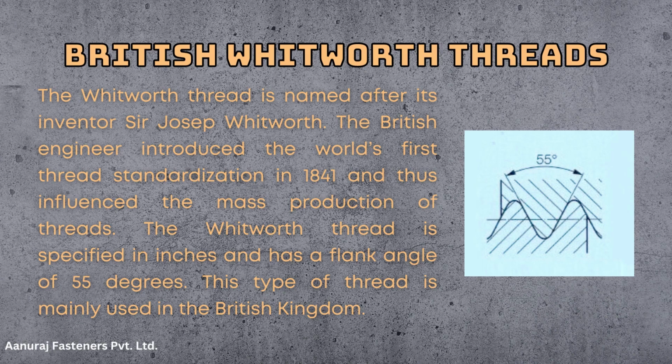British Whitworth threads. The Whitworth thread is named after its inventor Sir Joseph Whitworth. The British engineer introduced the world's first thread standardization in 1841 and thus influenced the mass production of threads. The Whitworth thread is specified in inches and has a flank angle of 55 degrees. This type of thread is mainly used in the United Kingdom.